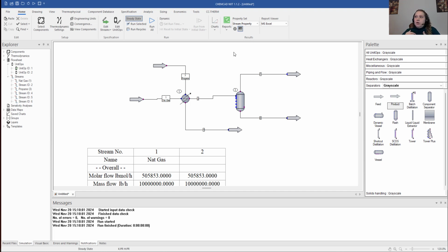Just like that, little by little, that's how you build your process simulation, adding in complexity and solving as you go along, making assumptions and solving as you go along. You can see how I had made a bad guess. I was showing you that if I guess and check, it could be a long process, but I arrived at a conclusion, and then I moved on and added complexity after I was able to solve little by little, starting from what I didn't know and figuring things out as I went along. And so that's the recommended best practice for ChemCAD simulation.